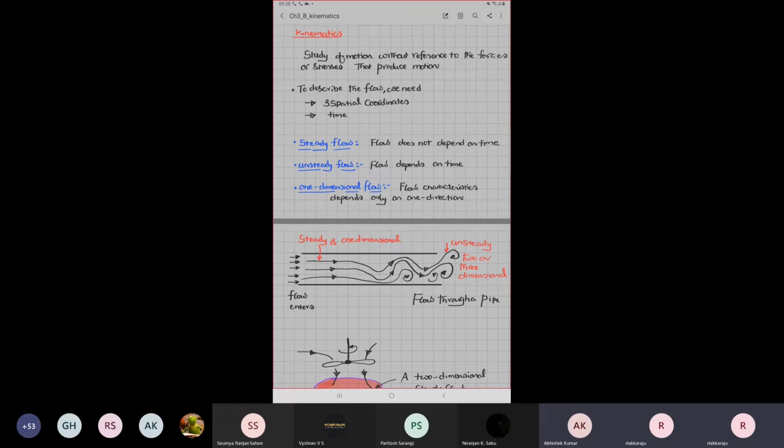At any given instant of time, if you are looking, the bob is always oscillating. You can always say it is unsteady. But on long-term average, the bob will be at its mean position. That long-term description we call stationary flow, or statistically stationary flow, or statistically steady flow.